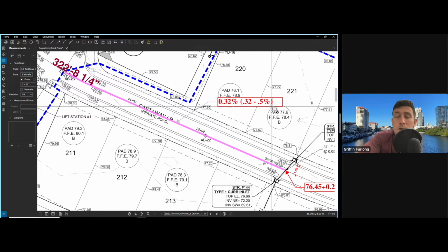You know, for the experienced engineers out there, once the algebraic difference between the road profile grades reaches 1 to 1.3%, you need to throw a vertical curve on there. But that'll be a whole other topic of discussion. Right here, we're going to work this grade from the low point all the way up to the high point, and let's see what we get.